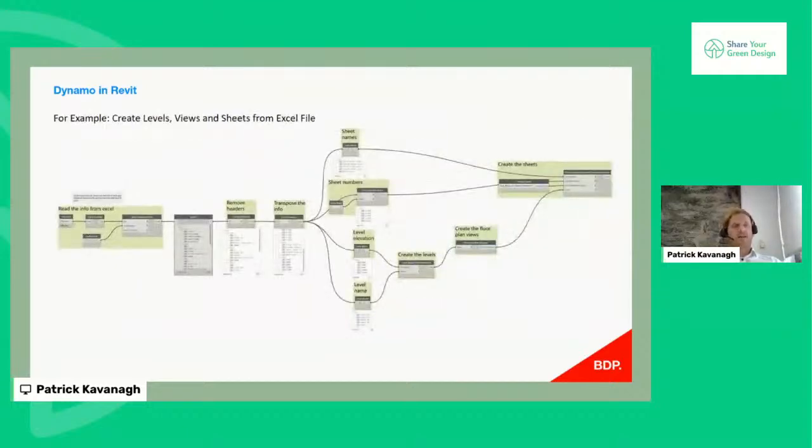and it gives solutions to real world problems that can be achieved quicker using computations. Again, I could spend an entire presentation talking about this, but just as an example, whether it's architects or engineers, you're going to have multiple drawings, particularly of a building that's complex, with different services and different floors. What Dynamo can do is, from Excel schedules, create levels, views, and sheets in just one click. And once you put that time in at early stages, you can then roll it out for every project.